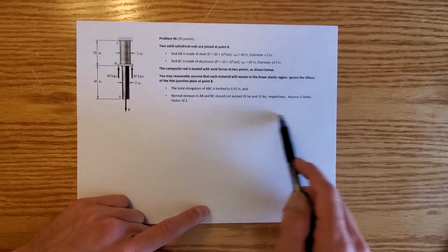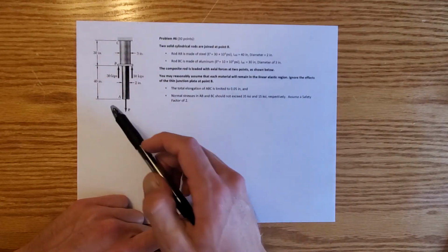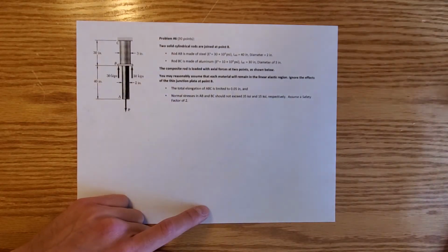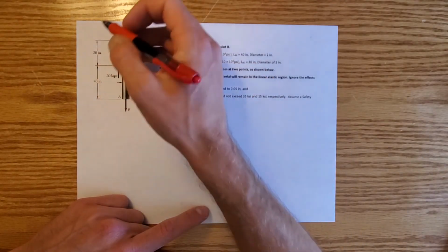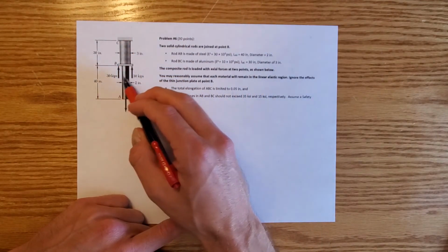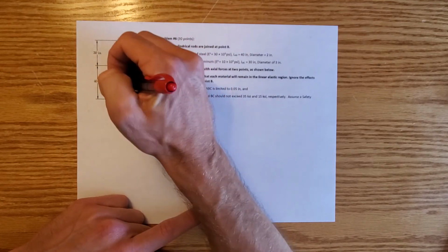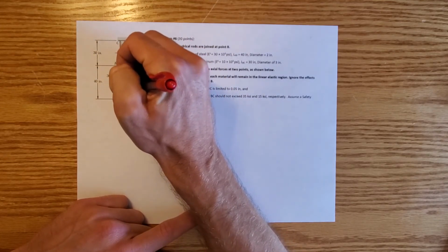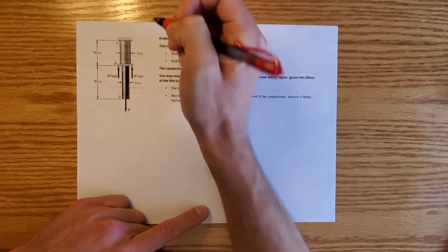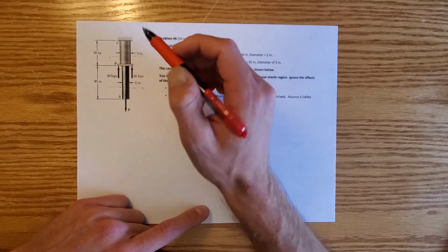Now the first thing you always want to do in a stepped rod problem is draw a free body diagram of your 2 stepped rods. The way we do that is very similar to what we did in internal forces: we're going to make a cut through this rod and through this rod at the top. We'll draw our red dotted lines to cut through both AB and BC, and we'll decide whether we should look up or look down.